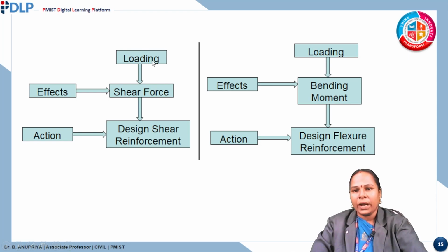So, when a load is applied over a beam, some internal reactions take place, and these internal reactions lead to shear and bending. To resist the shear force, we provide shear reinforcement, and to resist the bending, we provide flexural reinforcement. This is the main reason why we want to determine the shear and bending in a section,